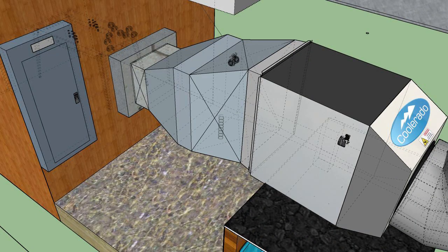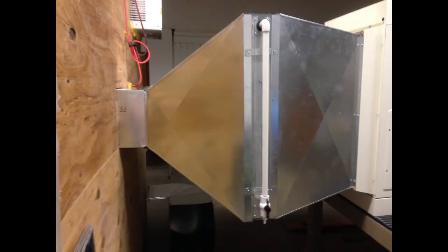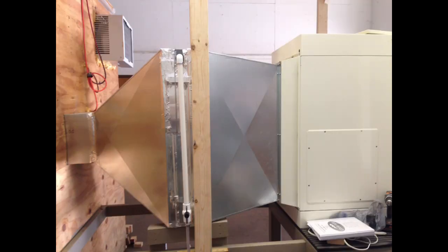The evaporative cooling unit consisted of two stages, an indirect evaporative cooler and a direct evaporative cooler. The indirect evaporative cooler was a Colorado Model M30. The direct cooling unit was constructed using a typical evaporative pad connected to a water supply to provide water flowing through the pad. A duct was used to connect the indirect cooler to the direct cooler, and then ductwork was used to direct the output air into the cooler room.